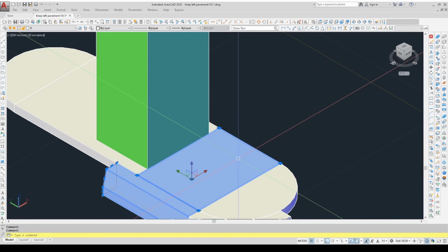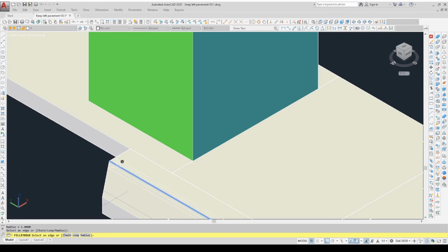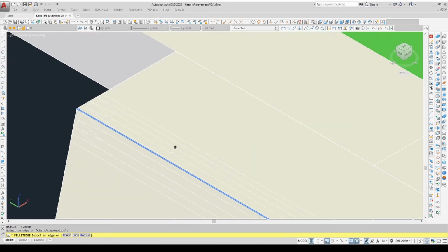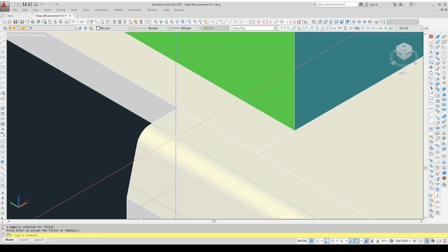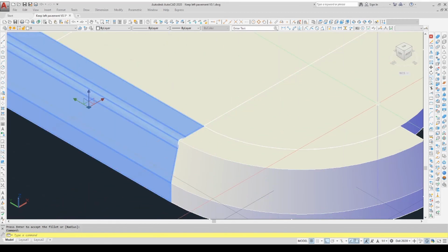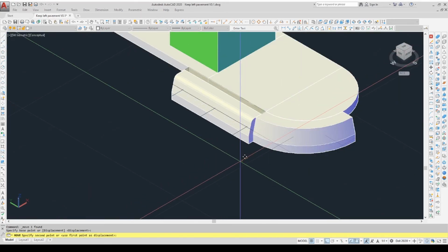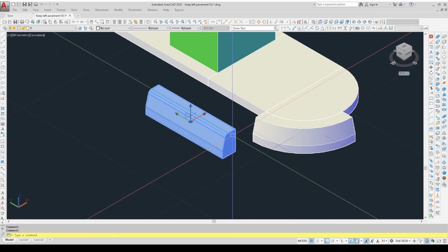And I think what I'm going to do is I'll show you one and then I'll do all the rest. So what we can do is select that command, we can go to this front edge here, and you can just see that it's kind of predefined it because it's remembered the last figure, which was a 1-inch radius. And for the front of that edge of that curve, that's probably quite good. So I will select that, and hey presto, magically it's created a curvy edge to that one. But what I want to do is to actually put it on the back edge to define that little trough of the fillet.